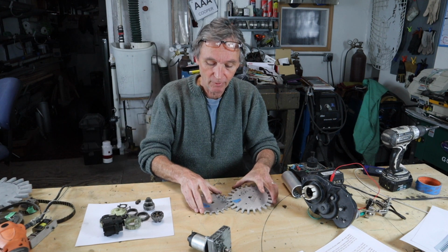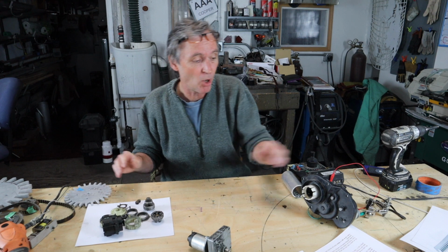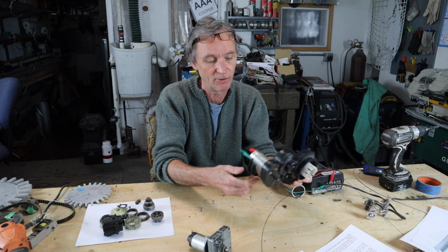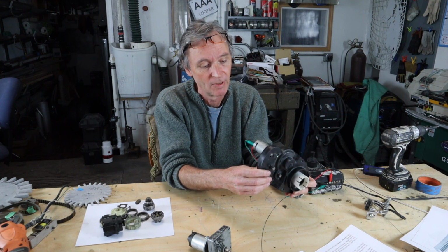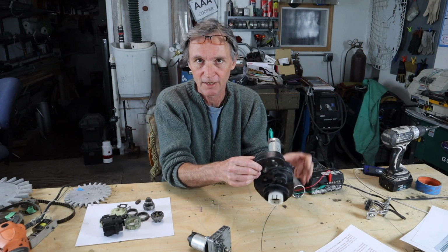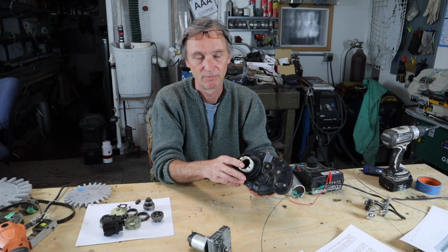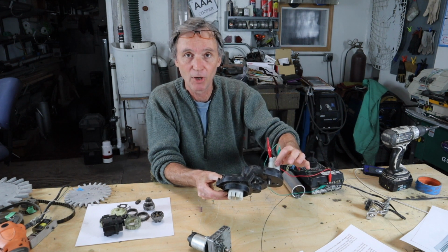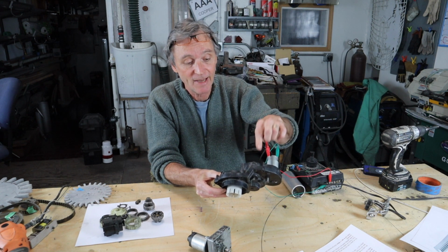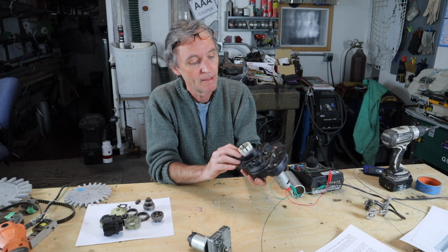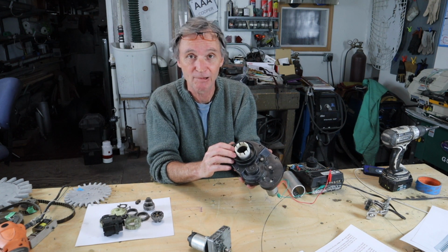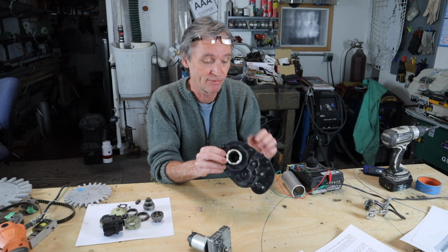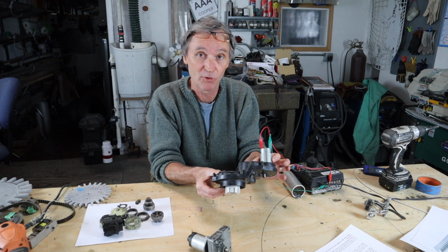And if you pack all those little gears into a box, it becomes, guess what, a gearbox. This is the motor and gearbox transmission out of one of those kiddies Barbie Jeeps that you see tootling down the street. And what it allows you to do is take a very small motor that spins very fast, gear it down through 1, 2, 3, 4, 5 different gear reductions. So you get the final drive going quite slowly but quite forcefully. That way you don't need a very big motor, and motors cost money.